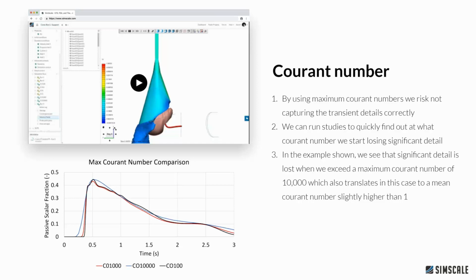So what we need to do is come up with a sensible limit to give to our simulation to say that, okay, these results are accurate enough for us. And that's what we could draw from this graph. That conclusion would be, I could be happy with a Courant number of 1,000, or if I wanted the utmost accuracy, and I'm willing to pay the extra core hours, then we could drop back down to 100 or maybe even lower. Bearing in mind, the lower the Courant number, the more accuracy we're going to see.